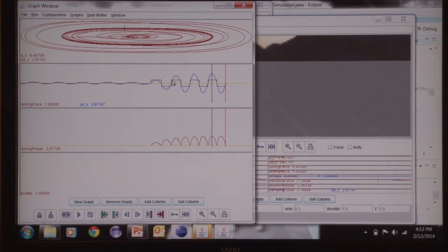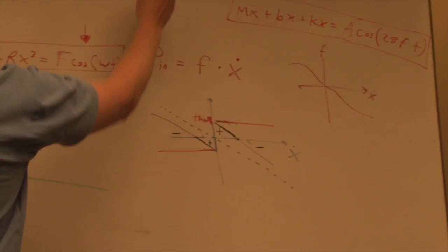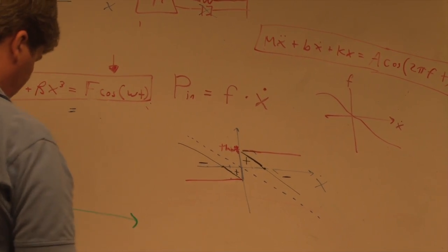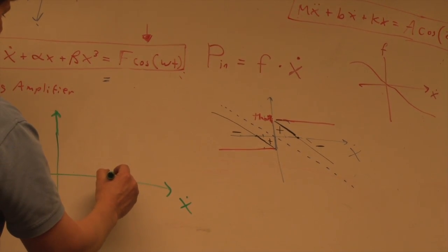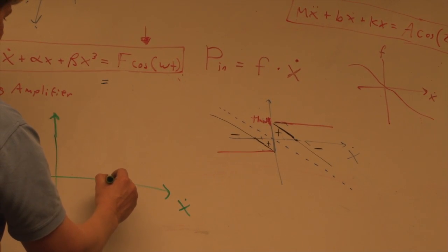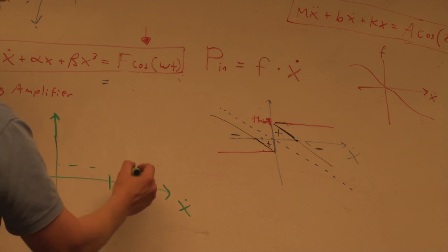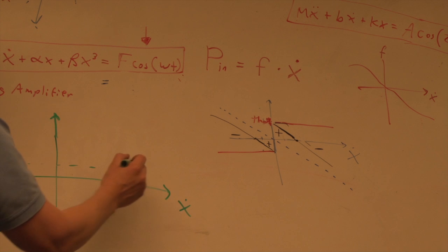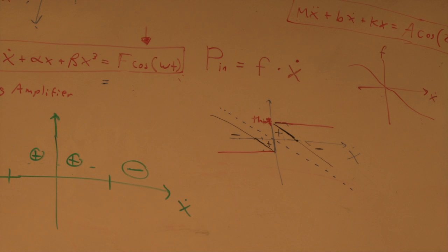But here's the key: with the mass spring damper system, at least with the stiffening spring, but maybe in more cases, if you look at the velocity x dot, as long as you have the conditions such that inside overall you're adding energy from here to here, and out here you're removing energy, negative power out here and positive power in here, then you'll get a stable oscillation.